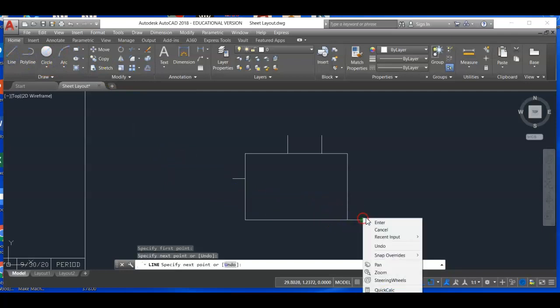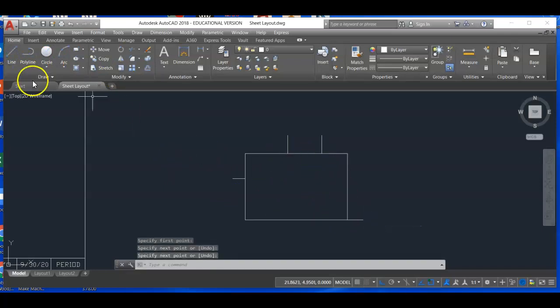Now these little handlebar things, these are snapping points because the corners need clipped. So you need a way to snap and draw a line. So let me move this line up. And the distance is going to be 1.5. Alright, now I have these snapping points. So I'm going to go to line. I'm going to snap here and snap here. And that will be that clipped corner. Go to line again, snap here, and snap here. Okay, so that's how I do those clipped corners.